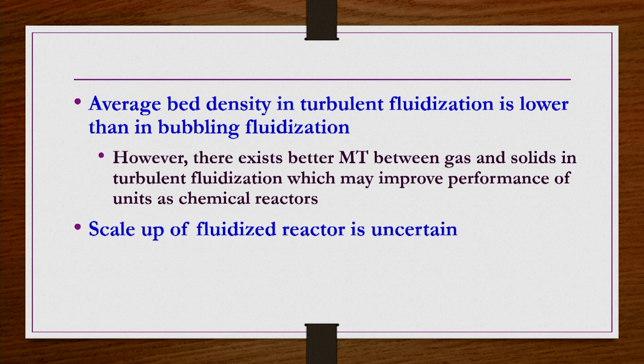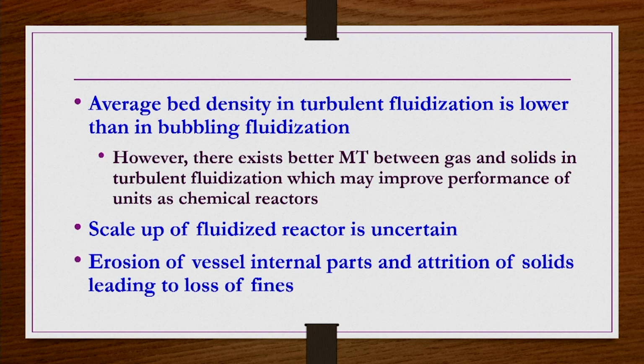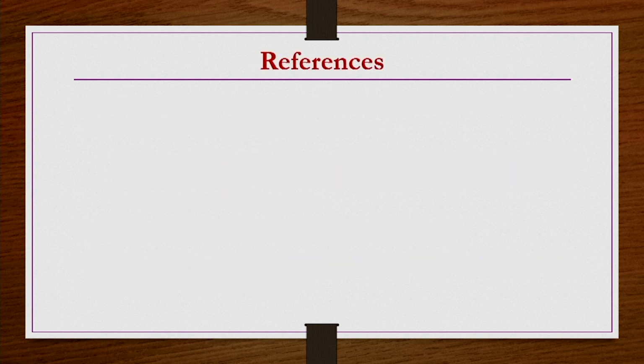Finally, a very important one: the scale-up of fluidized bed reactors is very uncertain. Also, erosion of vessel internal parts and attrition of solids leading to loss of fines sometimes occur in these fluidized beds, which may be taken as disadvantages in several cases.